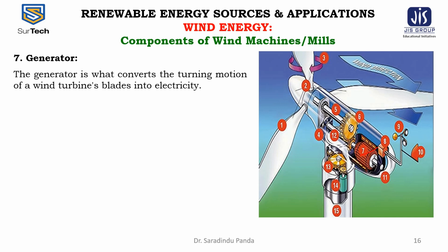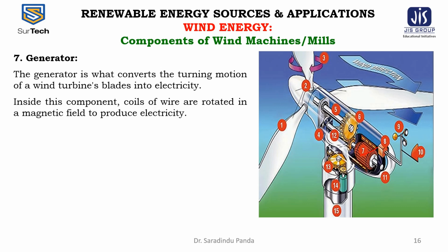The electric generator in a wind machine is attached to the main support frame and coupled to the high-speed end of the transmission shaft. Alternating current generators often run at 1800 rpm in the USA or 1500 rpm in much of the world to maintain the system frequencies of 60 Hz and 50 Hz respectively.